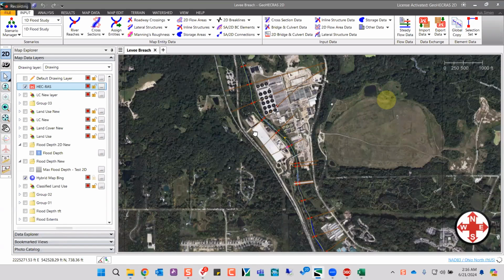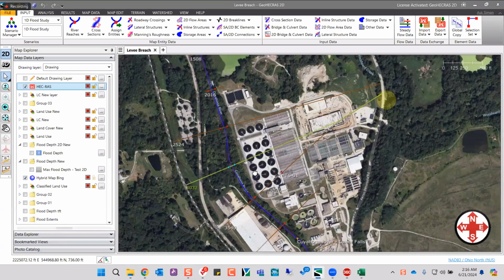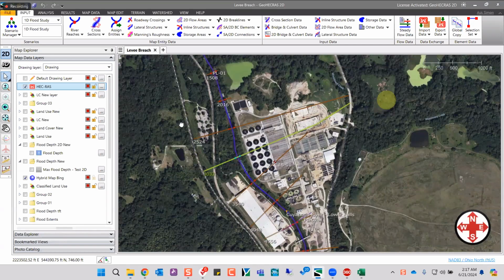When you work with your reaches and cross sections, that's your 1D model. When you work with your mesh elements, that's your 2D model. If you are dealing with an area that is considerably flat, chances of your water going onto the overbanks are pretty high, and energy dissipation and velocity are high on the overbanks. Those are your ideal cases for a 2D model. If your river follows a set course from upstream to downstream without causing much disturbance on the overbanks, not much energy dissipation, in that case it's suitable for your 1D model. Also, if you just want to see what area would get inundated, the extents of flooding, that would be ideal for your 1D steady state model.